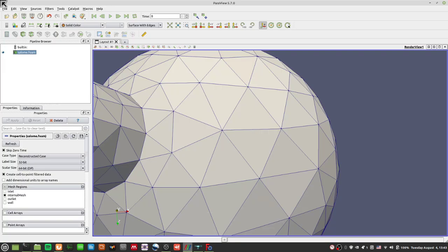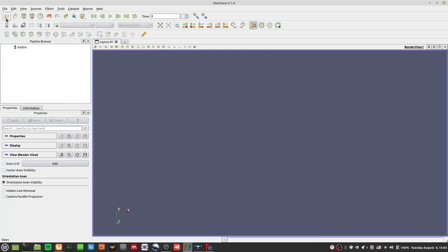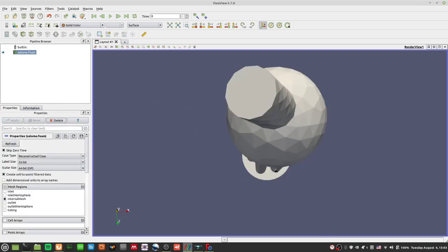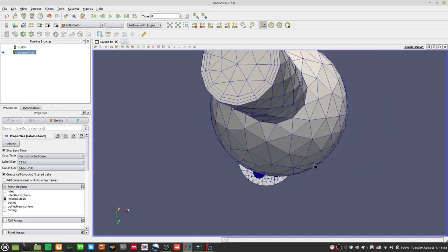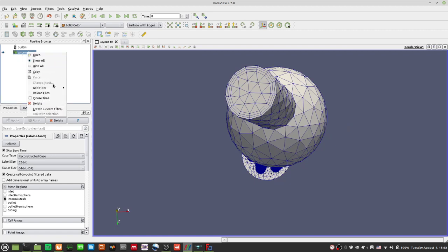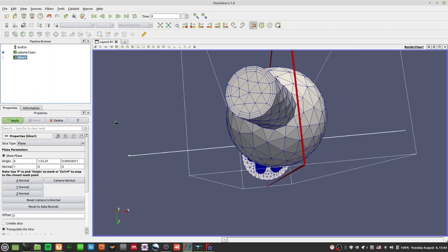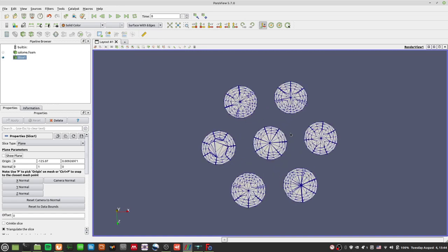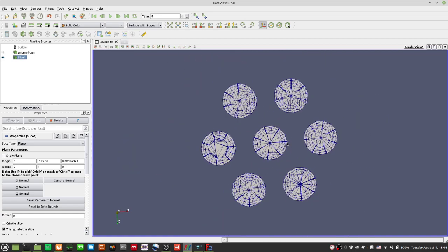We can look at this in what do you call it? We can look at this in this, what, ParaView. Yes, my goodness, how did I forget? ParaView. Okay, so this is what it looks like, and then we can just add the filter slice plot. We can do a Y normal. Okay, and we can do surface with edges, remove the plane, and you can see that the boundary layers are nicely added.